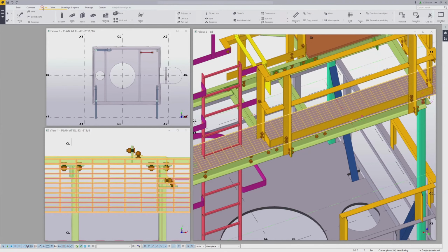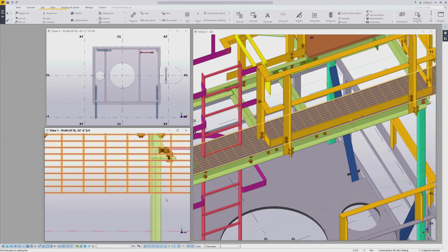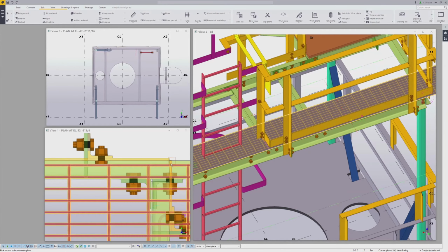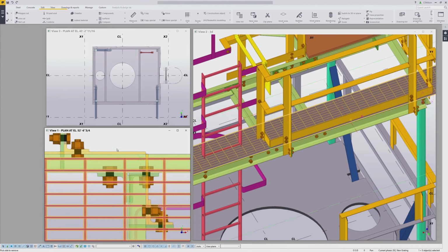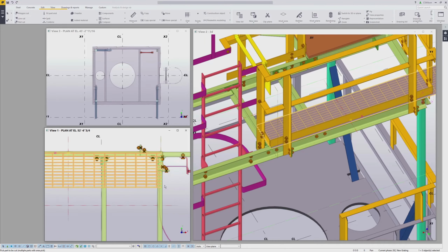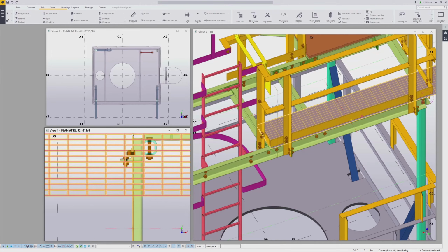So we go to Edit, and I want to use Line Cut, and I want to select this as my member, and I give a control point here and come back perpendicular 1/2 inch, and we'll give our second point perpendicular right here, and then the side that we want to remove is this right side, so we just pick a point there and that side goes away. We then come over to the other end and we do the same thing.